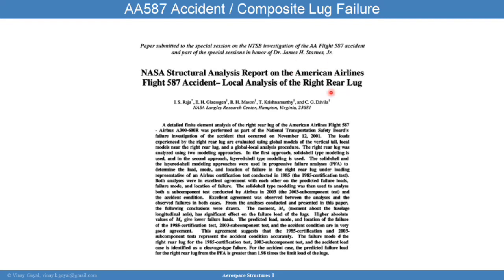What they're trying to do is evaluate the loads experienced by the right rear lug using a global-local analysis procedure. They use progressive failure analysis to simulate the failure mechanisms, and they also looked at loadings that were applied during the certification testing in 1985.